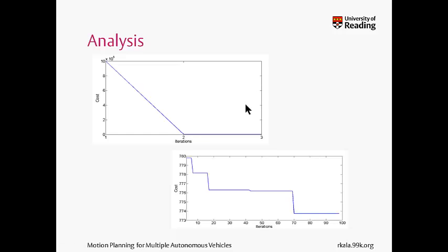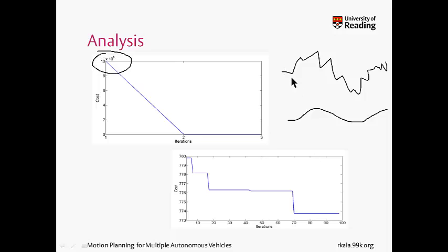And whenever I use anything like local optimization or any optimization technique, I need to show how the iterations, how the costs decrease along with iteration, or how the path improves along with iteration. Now one thing to notice is that I had first generated an RRT path like this, and then I use spline curves to locally optimize it to produce something like this. When I directly used spline curves, when I converted this to spline without local optimization, so the zeroth iteration, it came out to be infeasible.